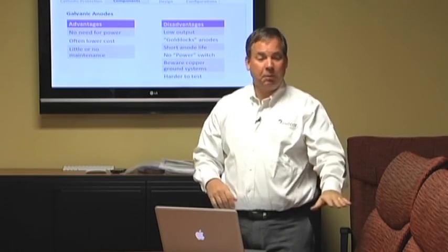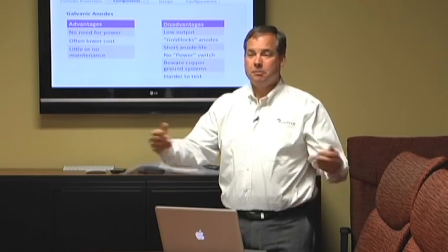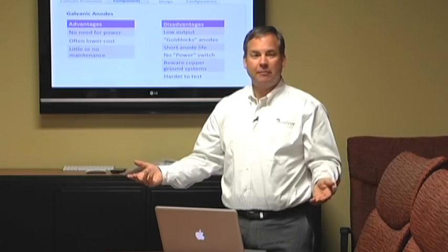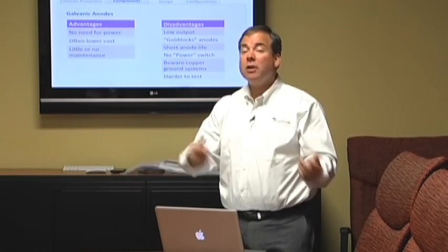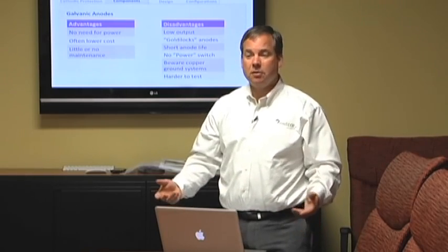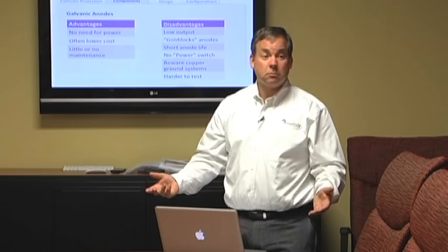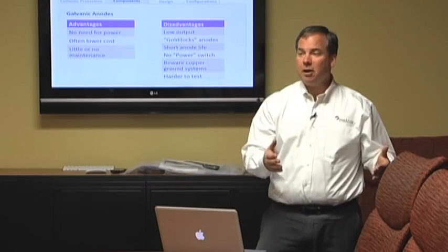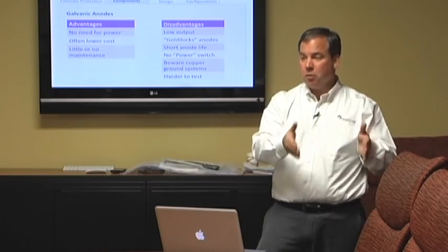The galvanic anode system is buried, the pipeline is buried, it's forgotten about 5 years later and nobody's testing. In fact, I got a call yesterday from a guy. He's got a pipeline protected with galvanic anodes. I asked him, have you had it tested? He says, no. Do you know it's working? No. Now, if he had a rectifier and a power supply, he could look at the power supply and say, yep, it's still working, it's still working.